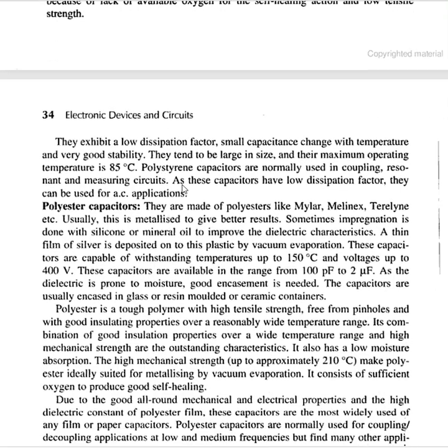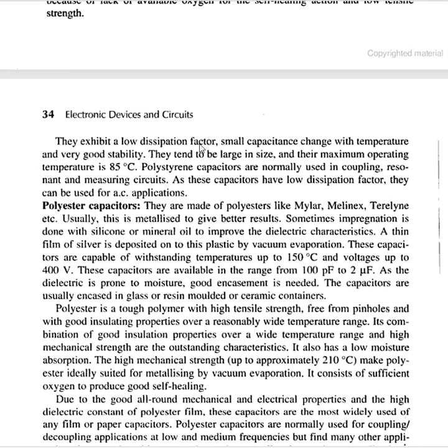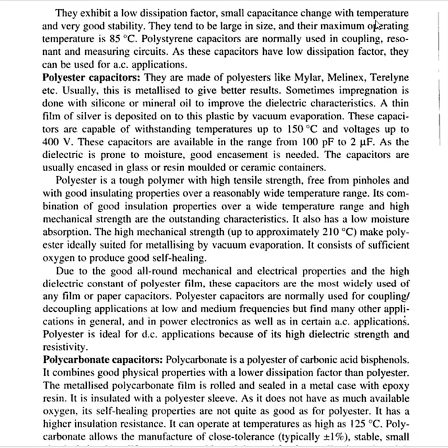They exhibit a low dissipation factor, small capacitance change with temperature, and very good stability. They tend to be large in size, and the maximum operating temperature is 85 degrees Celsius. Polystyrene capacitors are normally used in coupling, resonant, and measuring circuits. As these capacitors have low dissipation factor, they can be used for AC applications.